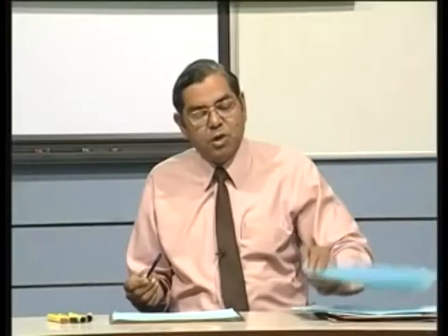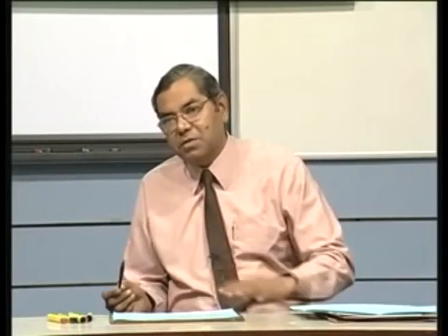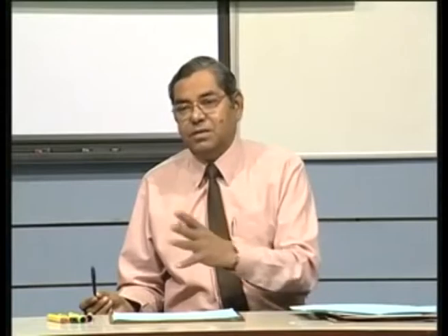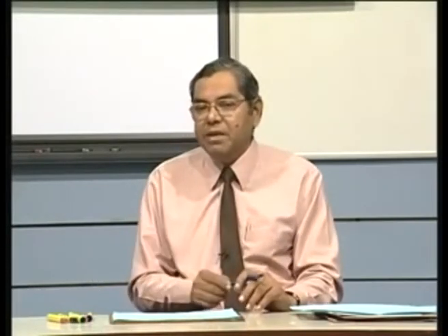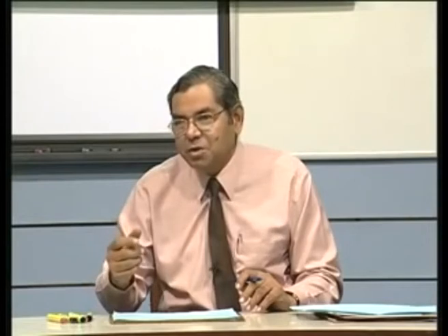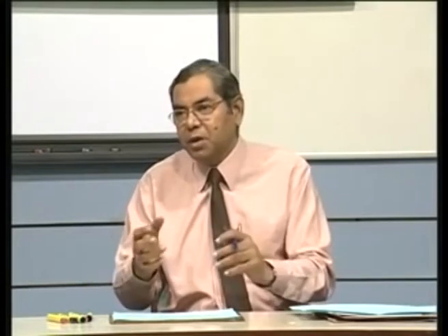So we would like this idle time to be as small as possible. An ideal situation would be when the line is perfectly balanced, that everyone is doing the same amount of tasks. But that is generally not possible. Why? Because the times are integral, number one, and then you have a constraint on precedence. You can't group everything with everything else. You are not weighing, for instance, rice, where you can put something here and make it exactly 250 grams. It's not possible to do that because you are dealing with individual entities which have to be grouped together.